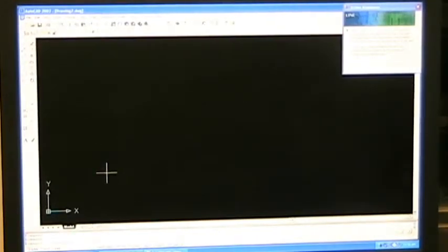And what you're going to want to do is frame in your drawing from the start. I'm going to choose the line tool, and I'm going to type in the origin 0, 0. And I'm just going to hit enter, and it's going to start a line for me from the origin. I can quickly type in 2, enter, and then hit 2 and enter, and it'll snap to 2 inches all the way around, creating a perfect box for me.